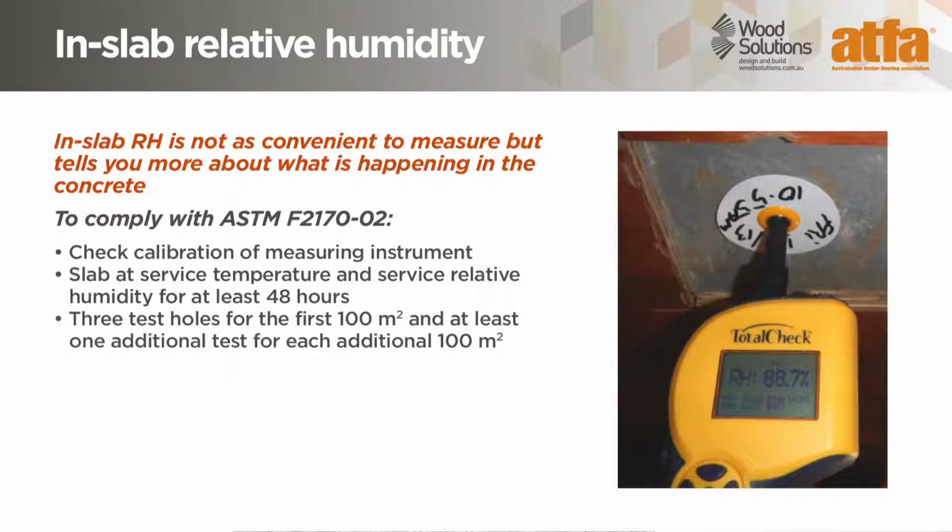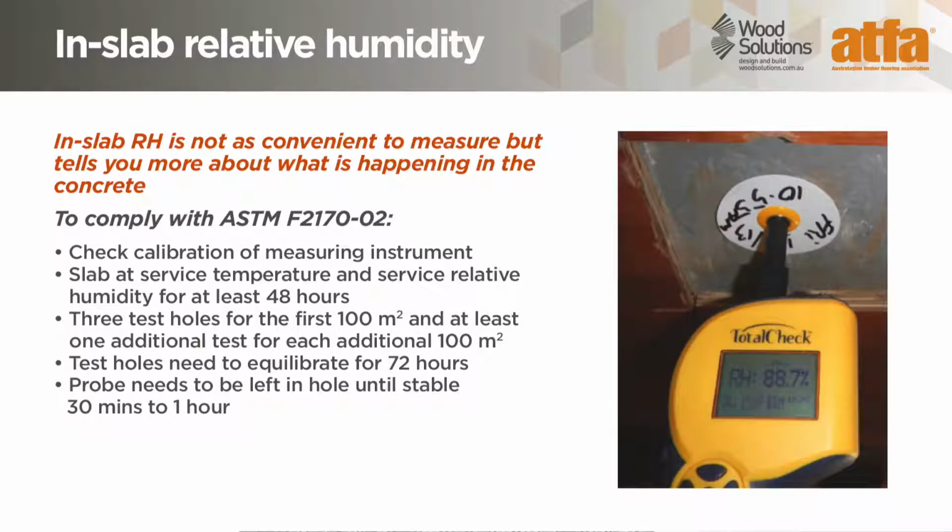3 test holes for the first 100 square metres and at least 1 additional test for each additional 100 square metres. Test holes need to acclimatise. Probe needs to be left in the hole until stable, and they must record results.